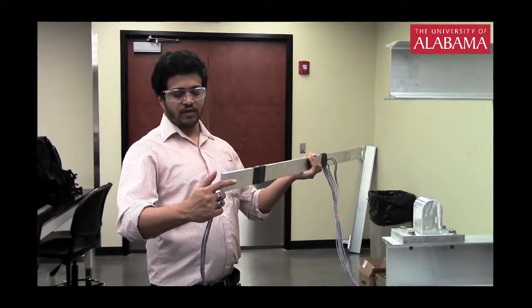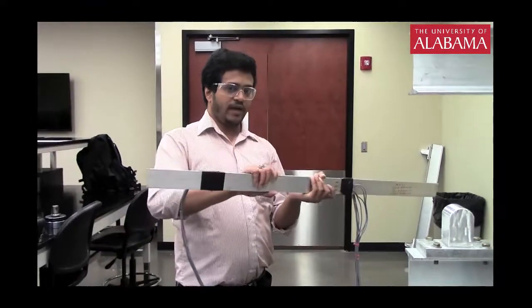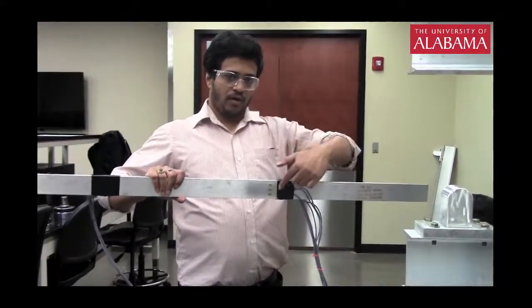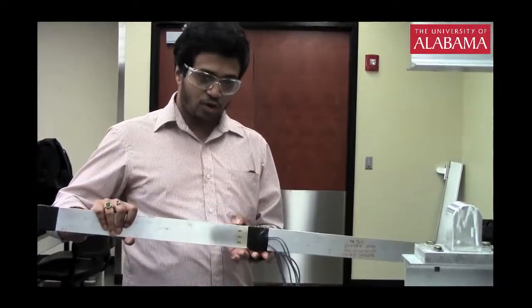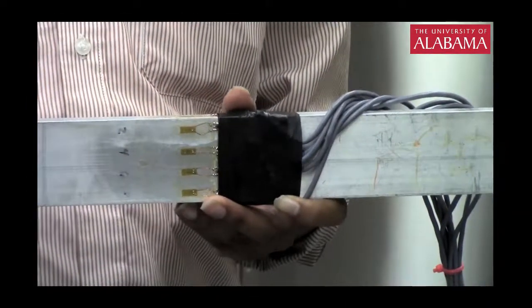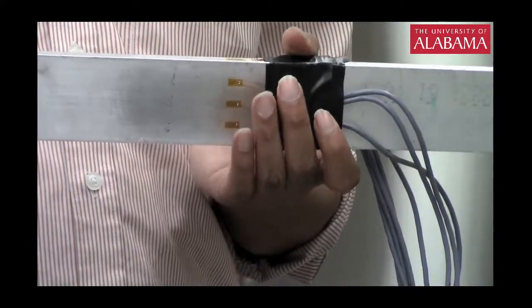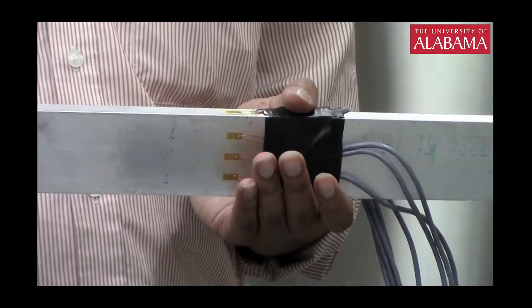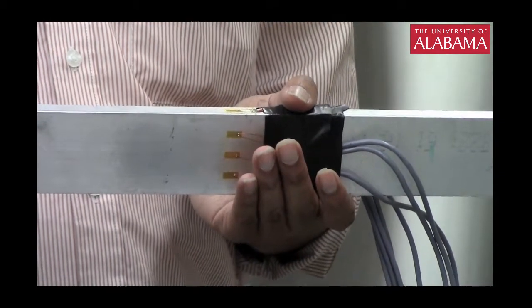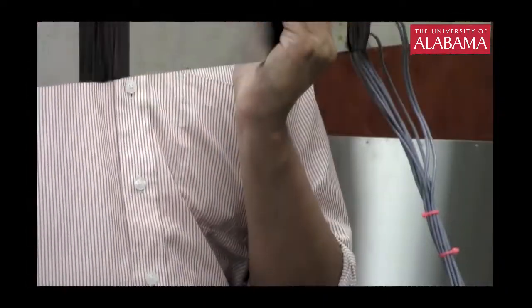So in order to find out what the bending stress is along the various cross sections, we have a lot of strain gauges on the surface of the beam. You can see there are 3 gauges on this side, 1 on the top, 1 on the bottom and 4 on this side. These gauges help me to measure the strain at various depths, or rather at various locations in the beam, and once we get the strain we can readily find out the stress. That way we are going to find out how the bending stress changes, or what is the variation of the bending stress along the cross section.